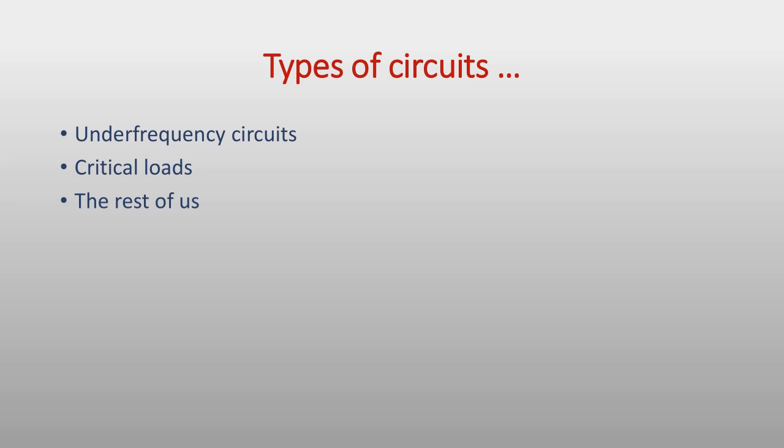So they don't even say, yeah, we don't like that Michael Lambert guy. We want to cut off his electricity. They cut it off at the circuit level. And there are three types of circuits in the grid. There's the under frequency circuits. These are protected circuits. They're put in, technically able to deal in an under frequency environment. They are spread out throughout the service area, in order to maintain some sort of equitable distribution. But they are there to help when there's been a load shed. They are there to help bring the system back online.